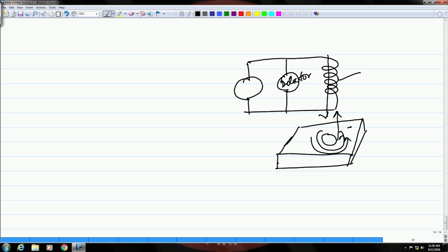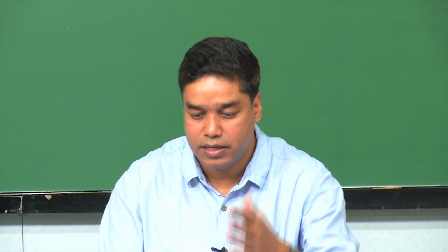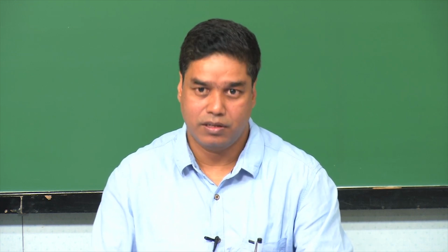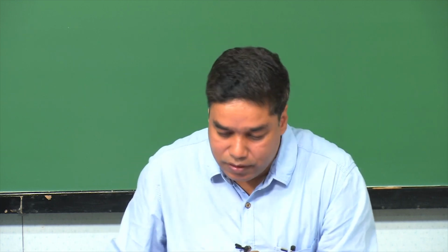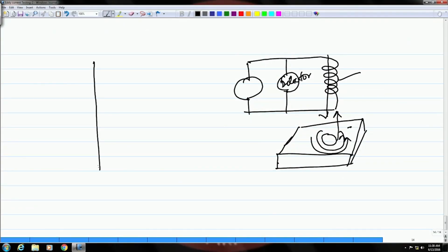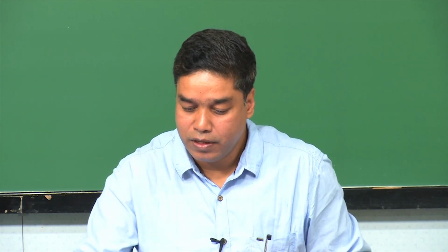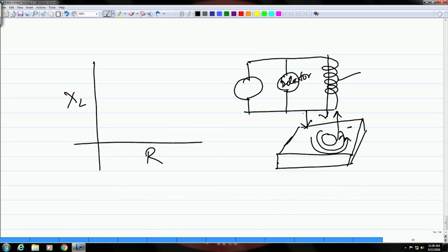And in order to sense this change, this parameter that we derived just now, impedance, will come into picture. So, what is going to happen when you bring this coil close to the sample surface? When it is close enough, then these eddy currents will start, okay. So, the distance between this probe and the sample surface is known as lift off.